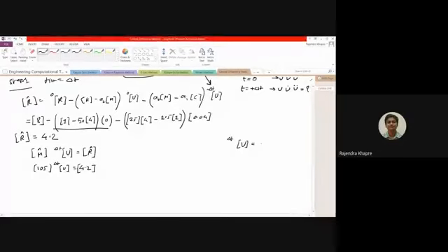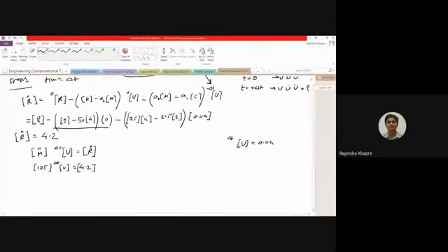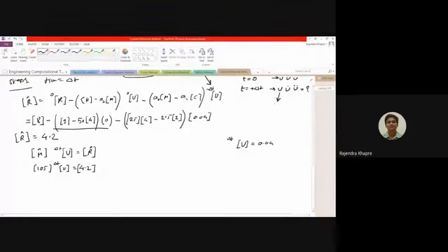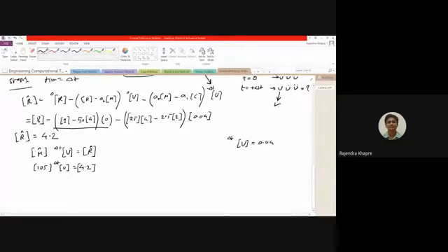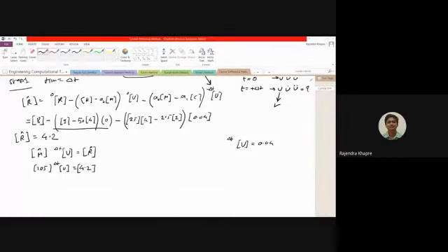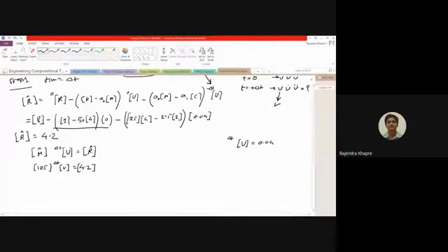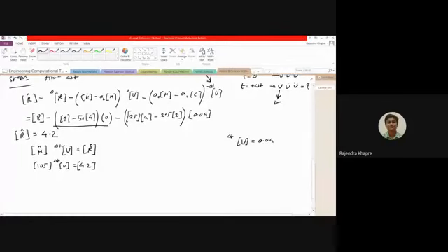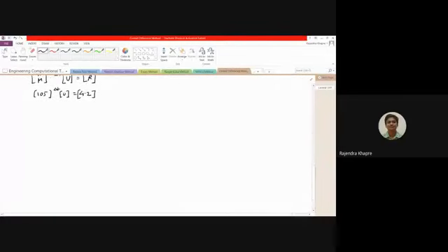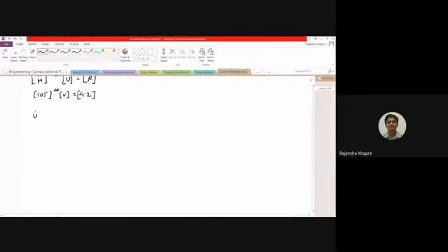0.04. So here you see there are three unknowns: u, u dot and u double dot. Out of this, the unknown displacement part is now successfully calculated. Now we have to calculate the velocity as well as the acceleration. In order to calculate the velocity, u dot, at delta t.